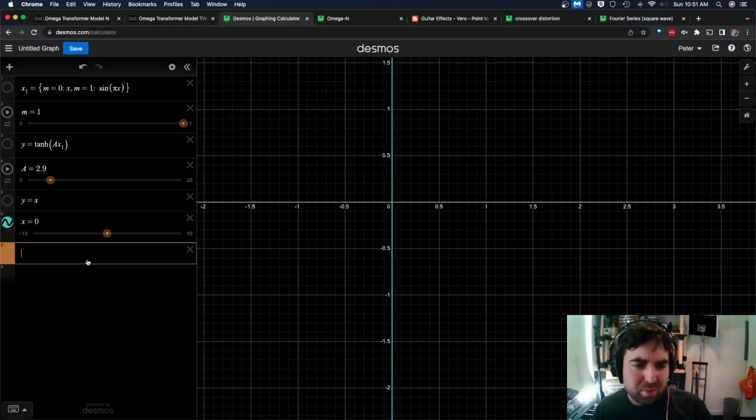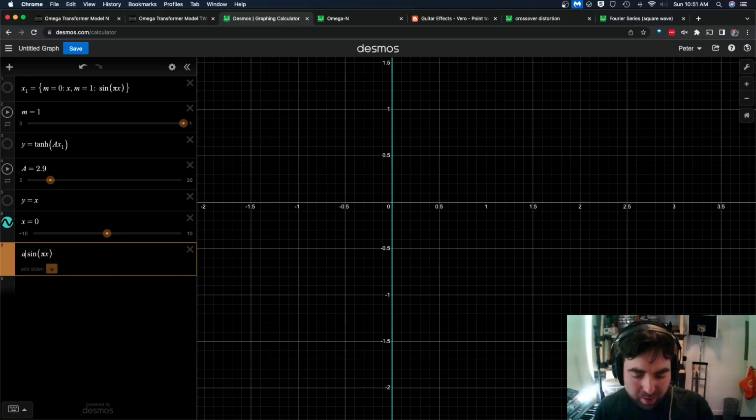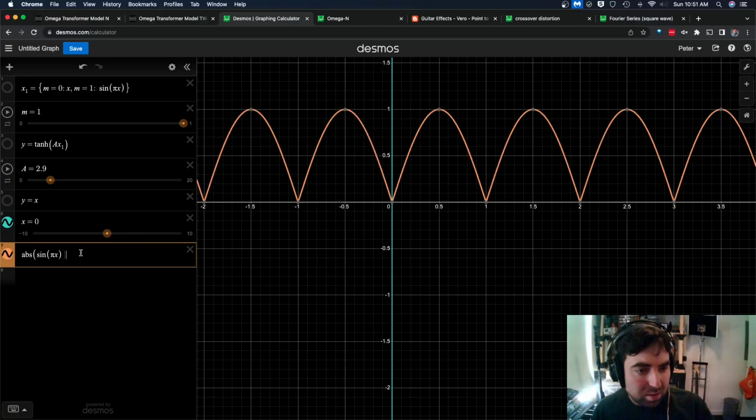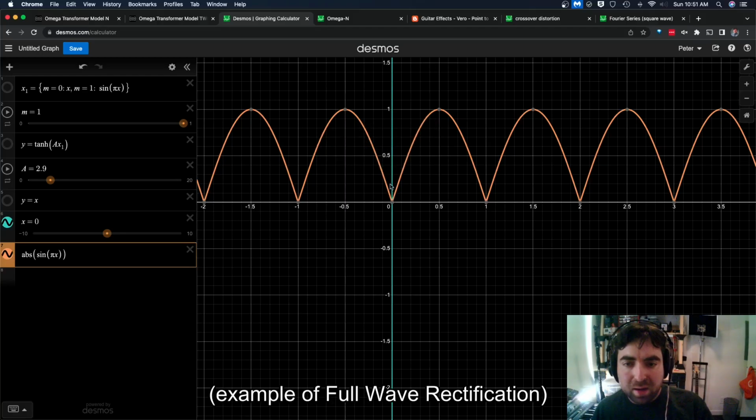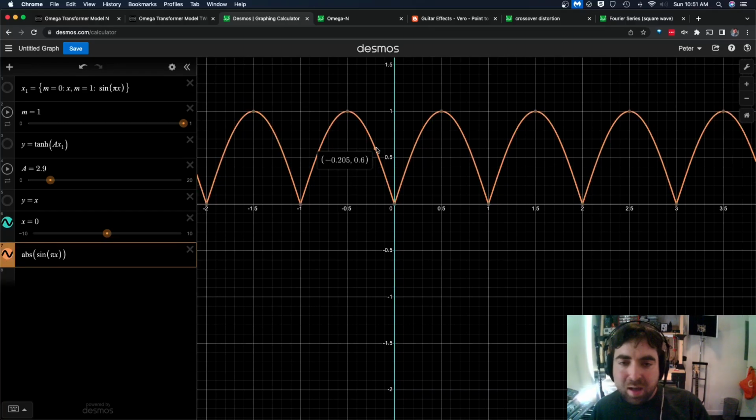An example of this would be sine pi x, our normal sine. But if we take the absolute value, so we're taking only the positive values and flipping the negative portion, then you can see along this axis it's the same on either side. Now we also only have the positive signal, so you'd have to remove the DC offset, the bias, but this would produce even order harmonics.